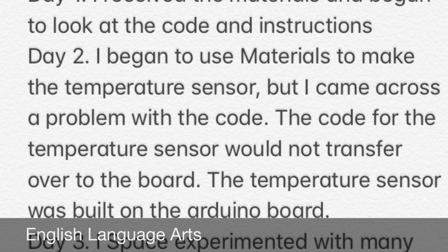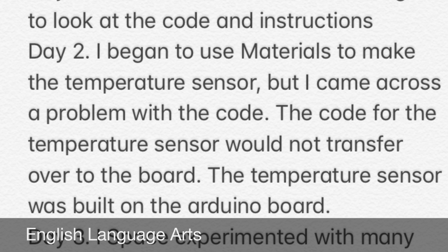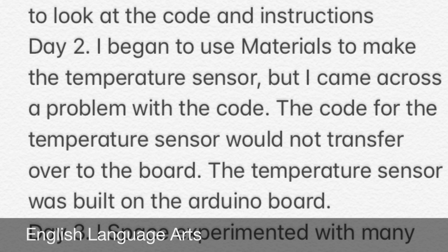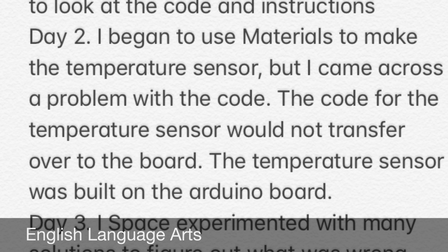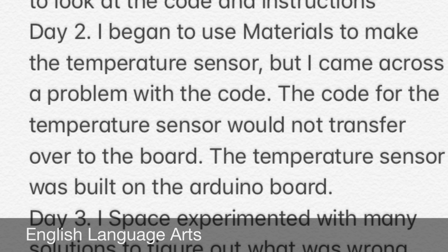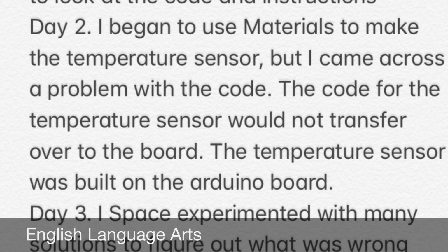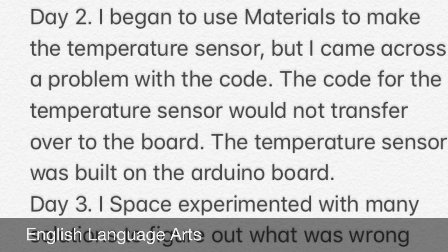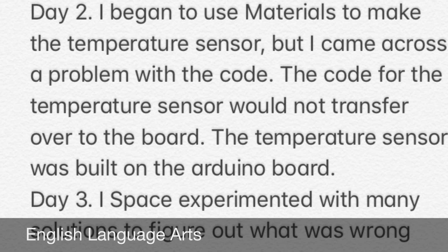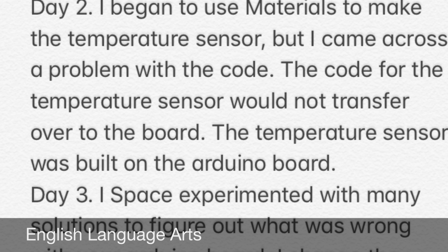Day 3, I experimented with many solutions to figure out what was wrong with the Arduino board. I changed the display component, re-input the code, restarted the Arduino coding application, and finally changed the port of the Arduino kit. I then realized after experimenting, the Arduino was sending the code to the wrong USB port, so it wasn't going directly to the Arduino board.